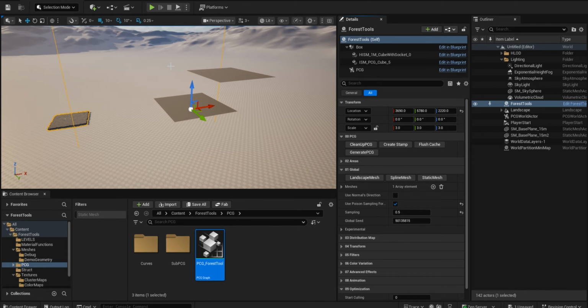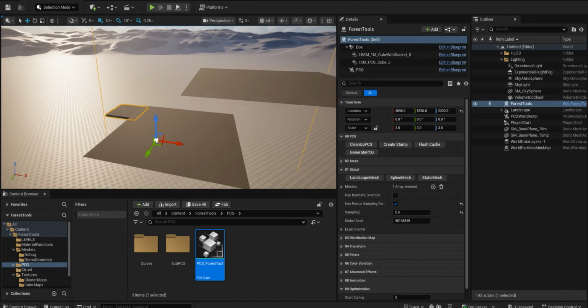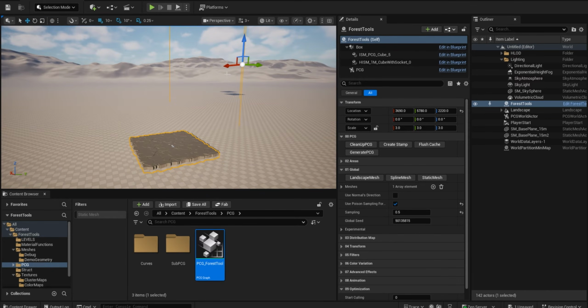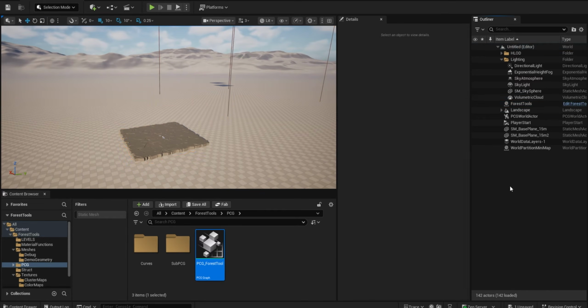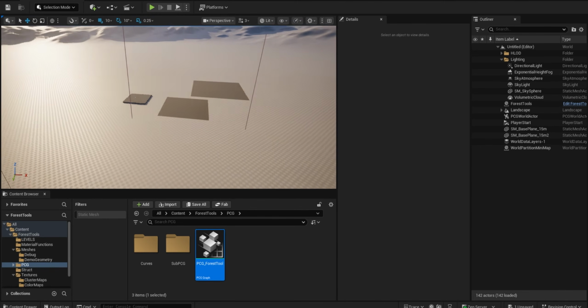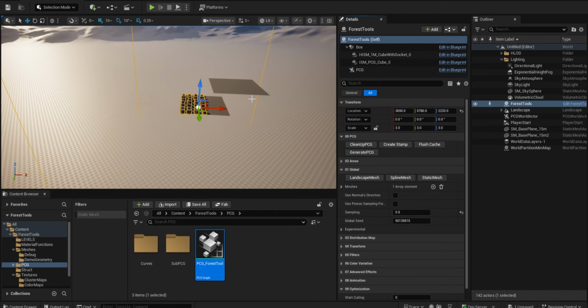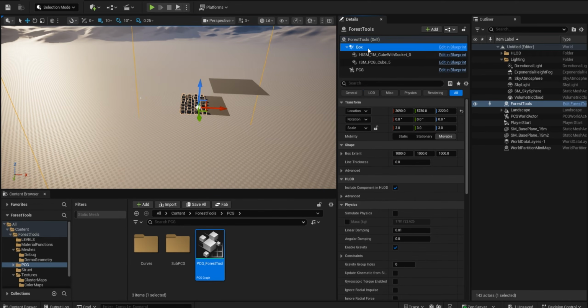It's still somewhat an experimental feature, so it's sometimes gonna produce a result at 0 coordinate space. So if you stumble into this kind of situation, you can go and modify the extent of the bounding box.